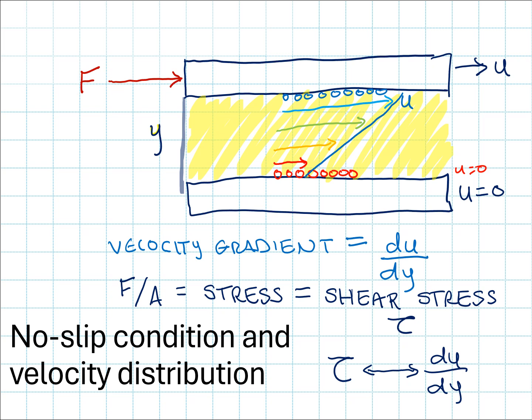And then I remember that aqua jogger example. So if the fluid that is touching the plate has a low viscosity, it's going to require less of that applied force to achieve the same velocity gradient than in a fluid with a greater viscosity, like honey, right? So I know that it's not just as simple as the applied shear stress being equal to the velocity gradient, right? I know that can't be true because I could apply the same shear stress to different fluids and see different velocity gradients. So there's got to be something else happening here.